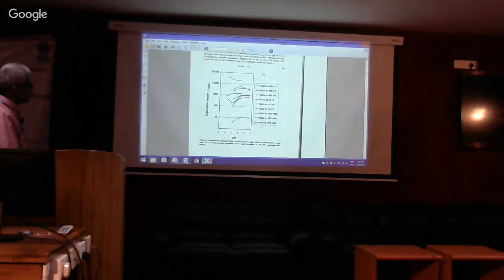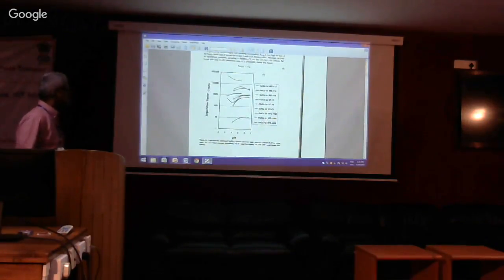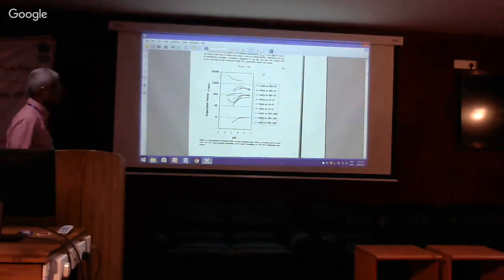Iminodiacetate we just talked about. Why is it selective? Then thiol, as you know, is sulfur based. Sulfur also has this capability of being able to donate a lone pair of electrons. And so with sulfur, what happens is that it is very good for mercury removal.